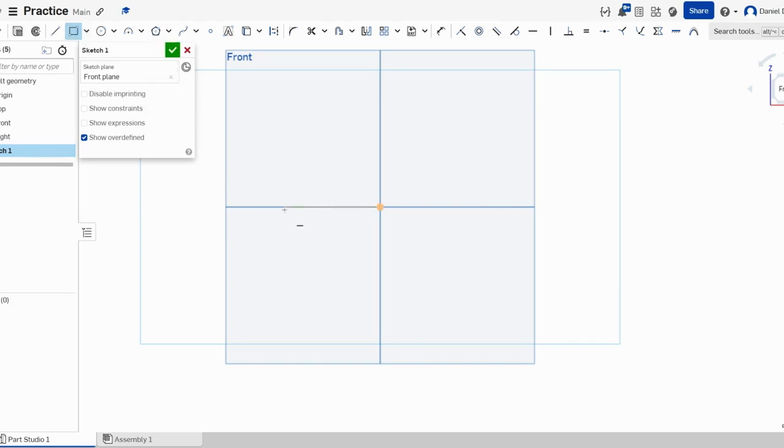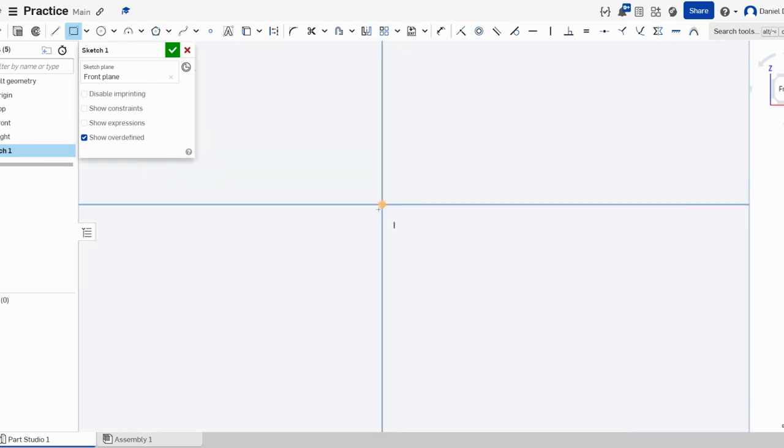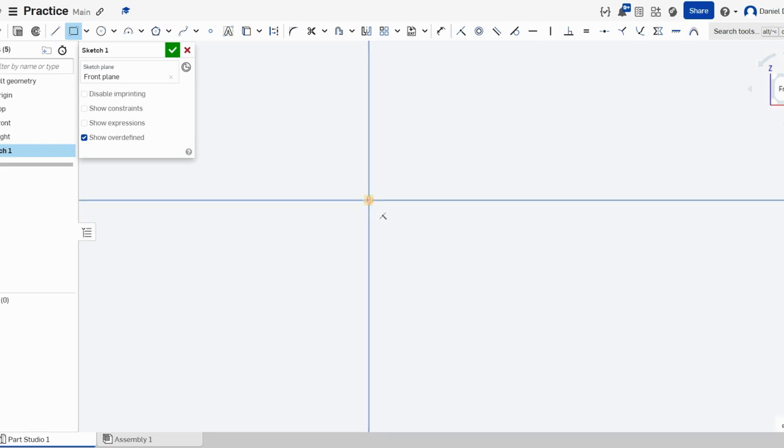Another principle in CAD is that we're typically going to try to make things certain dimensions. So it's important to have a reference on where your 2-dimensional sketches are attached. I'm going to attach this first sketch to this origin right here, the center. And you can tell it's going to attach my rectangle there when I draw it, because as I get close and hover over it, my yellow dot and box lights up.